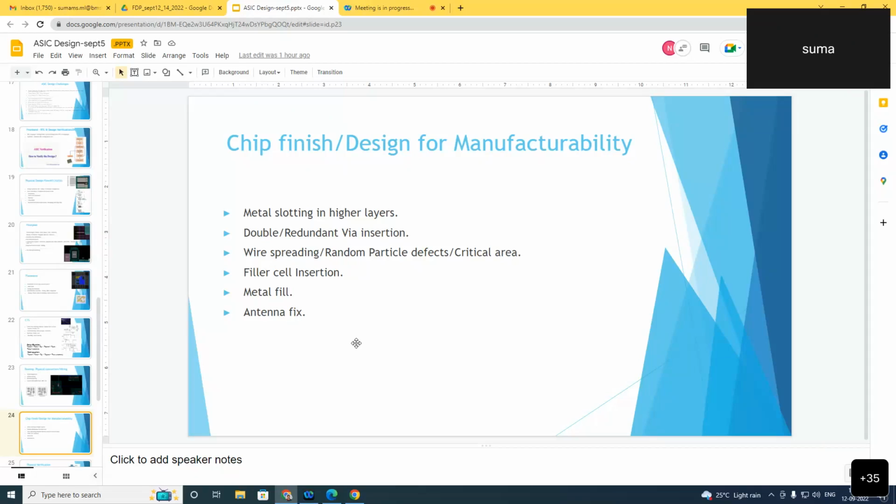Because of this routing, we may get increased capacitive coupling effect, which can disrupt the nearby nets also. So the designer must ensure that the metal fill is done without impacting timing critical nets. In other words, the fill needs to be timing aware.